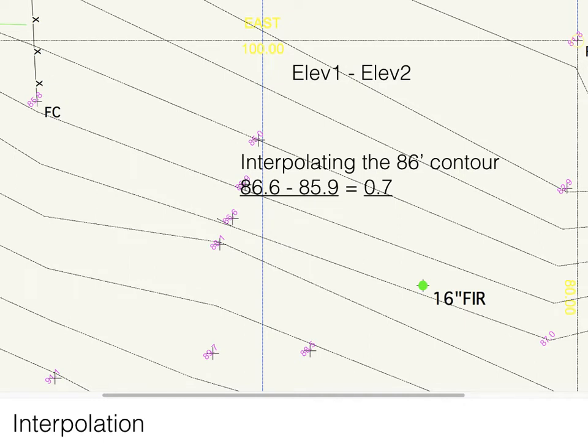and here's the work I did to take all of those contour lines and plot them on the site. And you notice that when you see existing contour lines, they're generally curved, and that's when you're using something like cameras to shoot them, and it's an accurate measurement. For our purposes, we just want to be reasonably close, and it's obviously easier to just draw some straight lines connecting spot grades at this point.